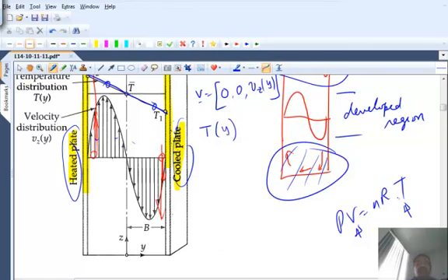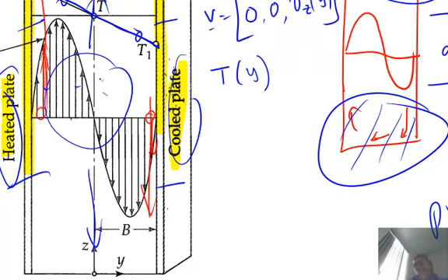If I keep the volume constant and keep increasing the temperature, I should increase the pressure. So if I'm uniformly increasing the temperature everywhere, the pressure will increase uniformly, so there will be no flow. But the expansion is causing this pressure increase because it's trying to expand, but it cannot because it's in a constant volume situation, right? So if I heat only this part, pump heat from both sides, no gravity, then I will see some sort of a flow. Why? Because the gas here expands and it has a lower pressure in the other region that it can move into, right? So you need to refine your question to pin down what it is.